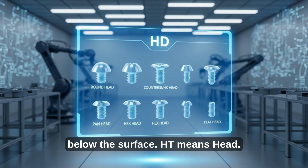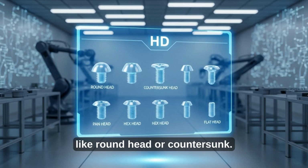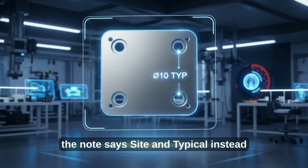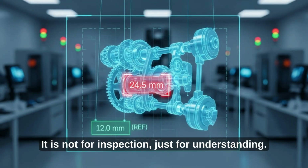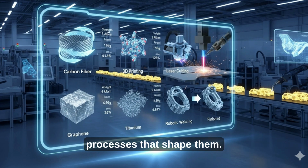HD means head. It tells you the shape of the screw top, like round head or countersunk. TYP means typical. If 4 holes are the same, the note says 4X and typical instead of repeating. REF means reference. It is not for inspection, just for understanding. Now let's look at the materials we use and the processes that shape them.